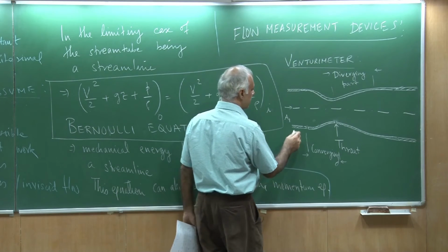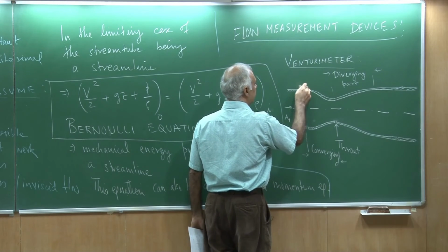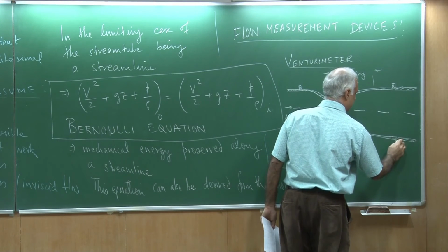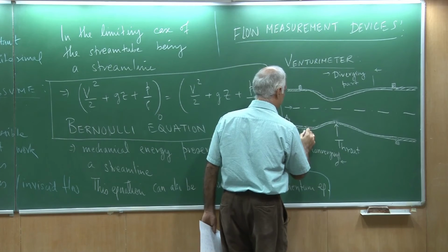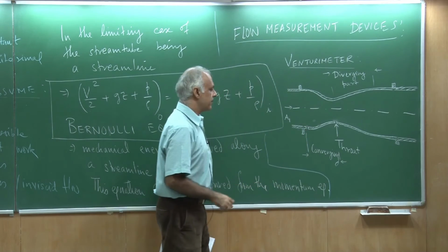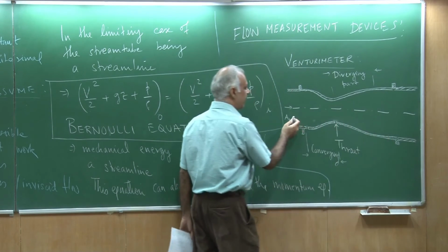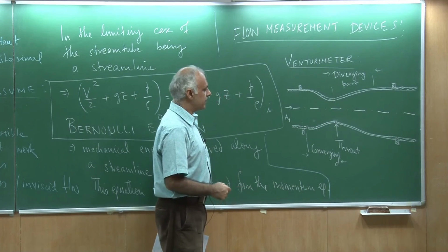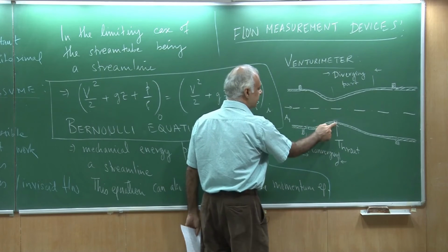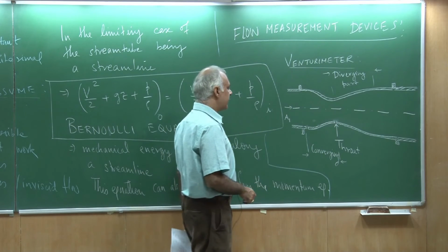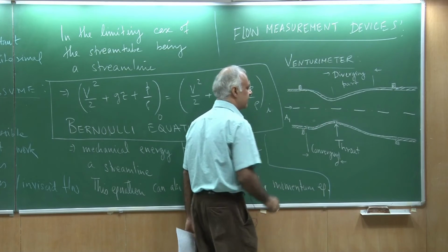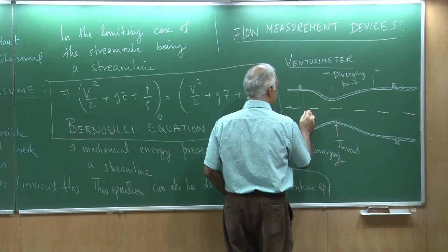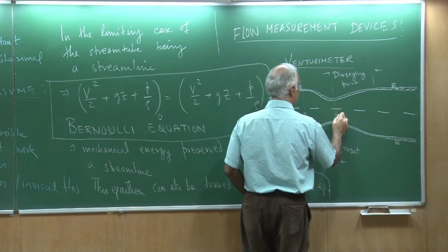So just to show you that actually this is a different pipe, okay. So the Venturi part is a different device compared to the pipes, and I have just inserted it between the pipe which is carrying the fluid. Okay, so I have put two tappings here, two small holes, and I can measure the pressure here. So let me call this section 1, and this I am going to call section 2.